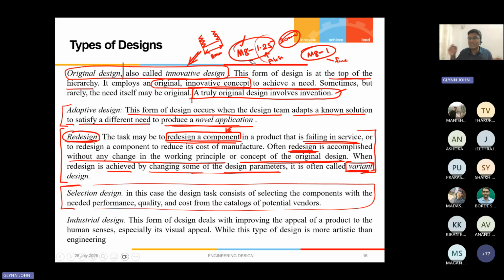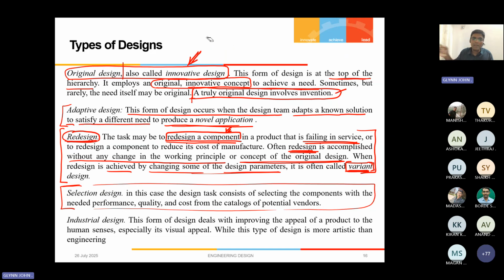While you specify the components in an exploded view, you simply mention this. And when you prepare your bill of materials, right, you mention like this, then there's no chance of making an error. So whenever you pick a screw, automatically you have to mention the outermost diameter and the pitch and the thread. And when you say M, it's metric, right? So similarly, you have inches also, right? So depending on what you want, you have to specify clearly. Otherwise, yes, there's a chance of going wrong.